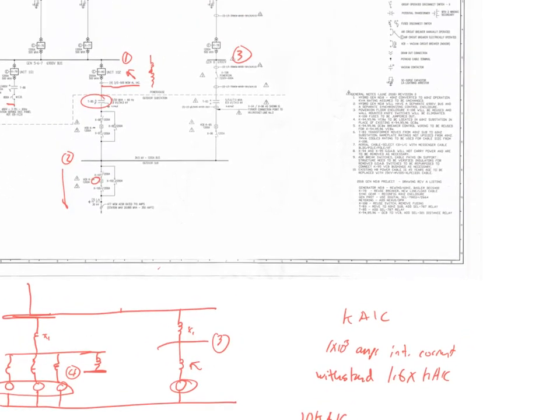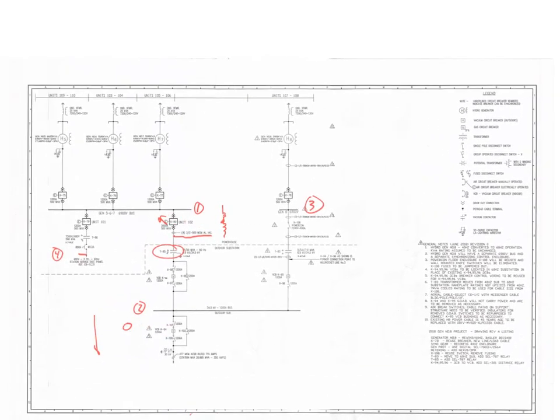What does matter a lot more is our zero sequence, because those do sum to a non-zero value, and they do need to have some flow. All right? So you see here, I have a connection to neutral. And here, and here, and here. So I'll just call those the same value, some neutral impedance. Let's just say they're all equal to Zn. They don't have to be, but we'll just make them all equal to Zn. So the generators themselves don't care about zero sequence. It's really how they are connected to neutral. If they are connected, great.